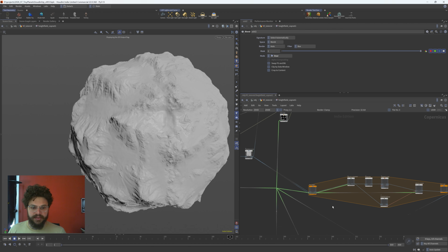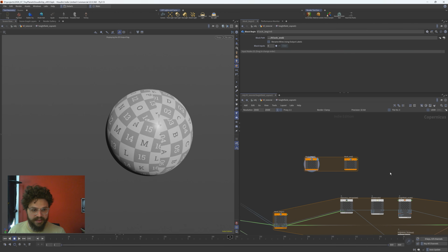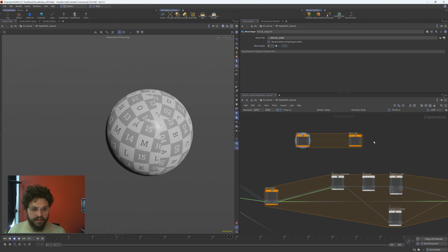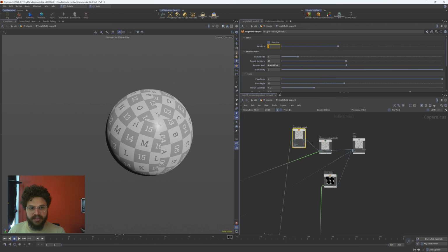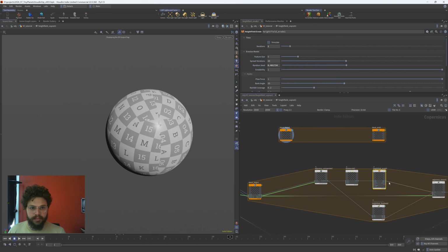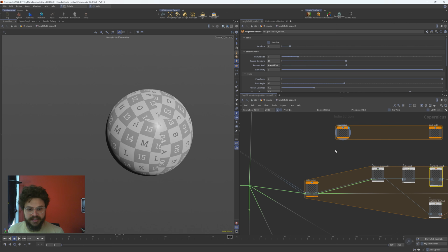So what I tried to do here is, instead of running the height field outside of a block for 7 iterations, I run it inside a block at 1 iteration and then use the adjacency extrapolate node every time to try to minimize the amount of seams that occur. So the more and more erosion occurs, the more and more the geometry deforms, and the more likely you get those UV seams, or at least that's the thought behind this.